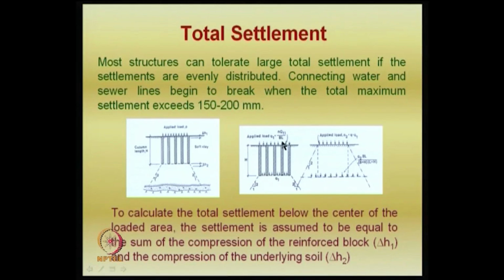So you can see the load here is the load that is applied, and the area is B into L. Say, for example, assume that it is a tank foundation or some rectangular foundation, you have to put B into L properly, and it can even be a 1 meter length in the case of a pavement or highway embankment. You can just take it as 1 meter and do that.